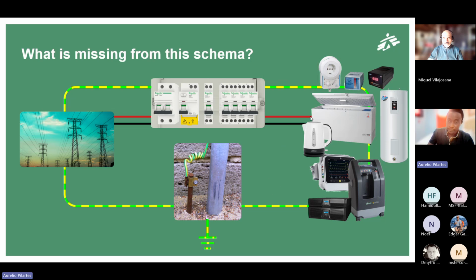So now that we are talking about AVRs, let's just remind very quick the difference between a voltage limiter, or how does each of these equipment work and what it does. So first of all, the voltage limiter will just keep monitoring your voltage, because as you know, all your appliances are sensitive to voltage fluctuations. And you have voltage fluctuations, especially if you are connected to the grid as your source. And these voltage fluctuations could be harmful for your devices.